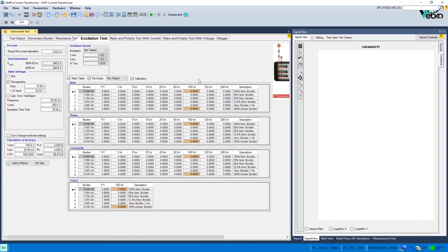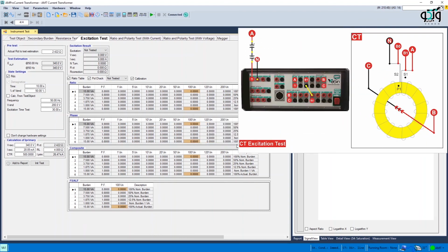Resistance measurement. By checking RDC, the winding resistance is measured using the voltage application and current measurement method. For this test, the capacitors are bypassed using binary output 1 and DC voltage is applied to the CT.